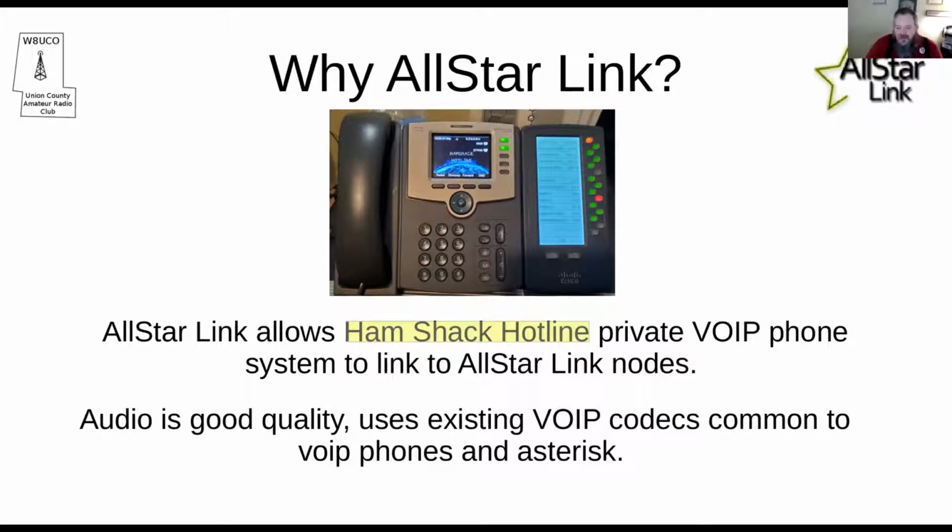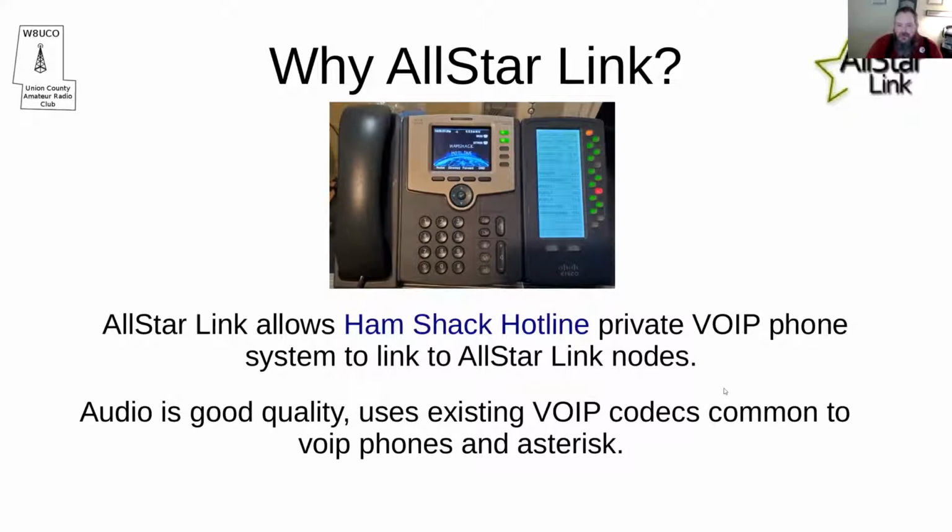And also with any link system, remember to pause after keying but before speaking, to allow all the repeaters that are connected to it to key up before you start talking. So I personally think that's a pretty innovative feature or use of Allstar Link.